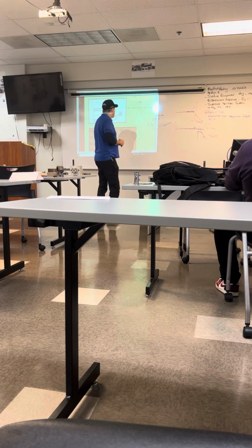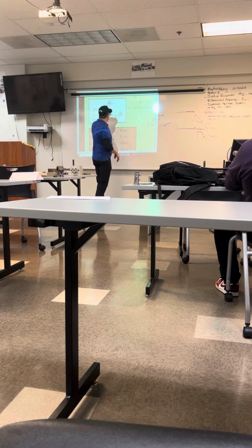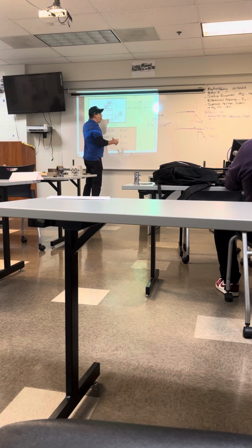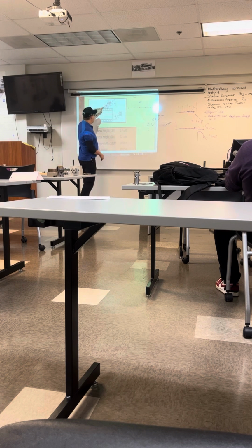So what happens is those descriptions, those symbols, describe in what direction the process is done. And that number here, that's the most important number. Does that make sense? What is that number? The amount of roughness. This one is 63 micro, 63 micro. Millionths? Millionths. And this one is what? 32 micro. 32 micro. What surface is smoother?